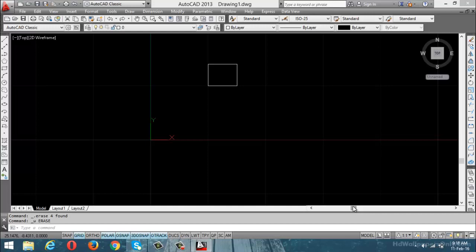Okay, now see here, same start point 10 comma 10, same design, a 5 by 4 room, using start point 10 comma 10. Same thing, L enter, specify the first point 10 comma 10. Any method, the first point is the same. Next, what are the x and y values for this line? 5 comma 0. So I am going to enter at the rate 5 comma 0.